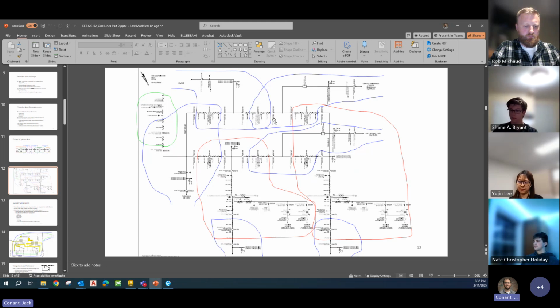Because it's not just the two breakers and the line we're worried about. We're worried about this tertiary winding. There's all sorts of internal things to the transformer that need protection or do the protection for the transformer. But in this case, for the high side, we connect in between these two breakers. So we wrap those two breakers. And on the low side, we have this series breaker. So we wrap that breaker, and our protection needs to cover the tertiary stuff as well. So that's our zone of protection for the transformer.